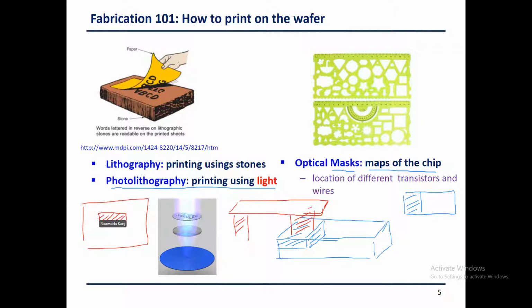So these are maps, just like we have maps for roads and we have maps for houses. We have maps for the different layers of the chip demonstrating the routing, yani all the possible connections at a given layer to be achieved from one location on the chip to another. Once those patterns are well designed and known, the masks are then used to transfer this information to print it on the chip, sort of to build the different layers that will eventually create a functional chip. That's the big picture that we want to look at.